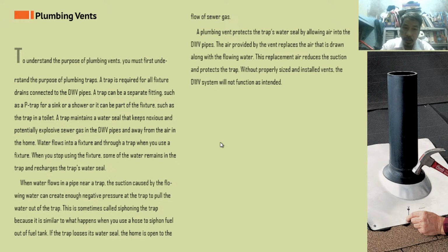There is always a potential for noxious or explosive gas. Okay? So unwanted gases. Not only the water closet. And some of the water remains in the trap and recharges the trap's water seal. Okay?